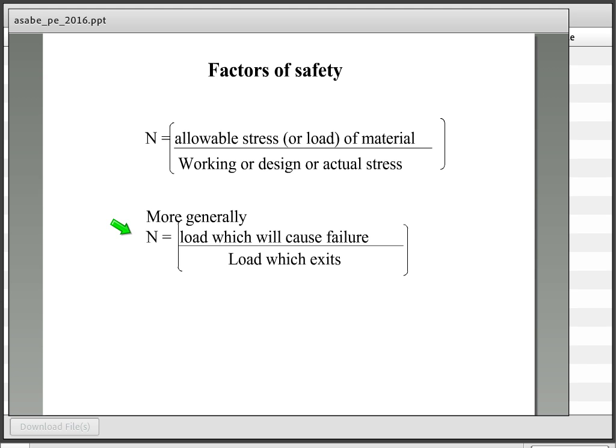no longer functioning properly. In other words, for example, if you had a shaft with gears on it that were loading the shaft, and if you simply had a shaft that had too much flexure in it for the gears to mesh properly, that would be defined as a failed design or an unsatisfactory design.